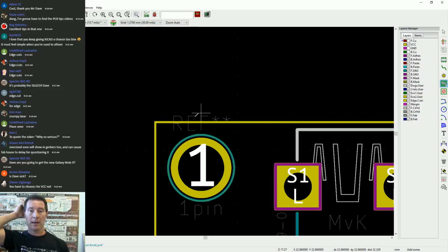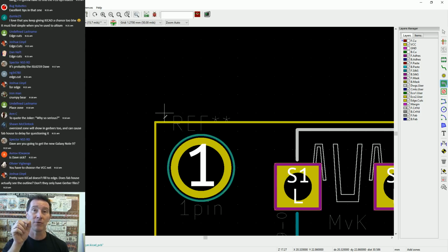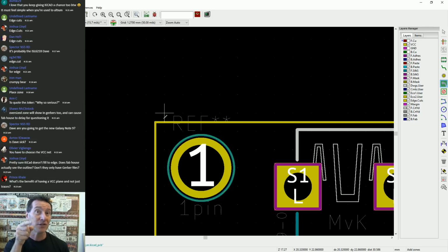But anyway, if you draw them all the way to the edge, like I can't, my snap doesn't go in there. It doesn't snap to object. Anyway, if you take your copper plane all the way to the edge of the board where the board gets routed or sawed or cut off, then when they slice or route through it, it can cause little burrs in the copper.